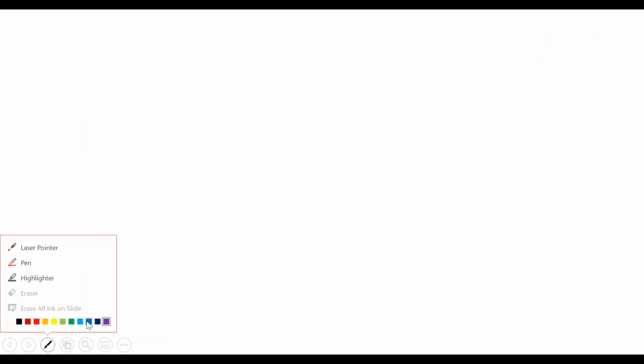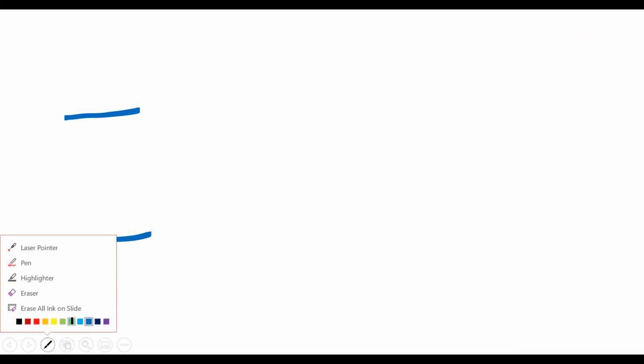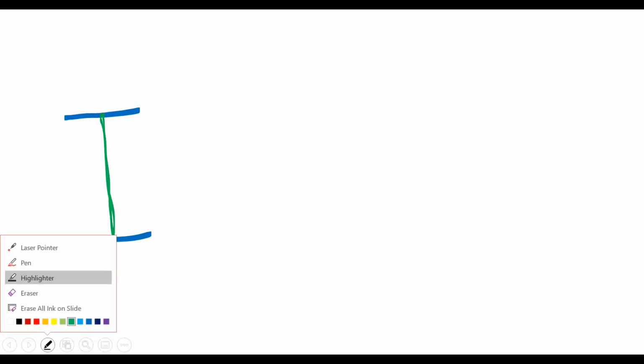First, you need to run VDD and ground, and N diffusion in green. Contact cuts are black, to make the actual contact between this and here.